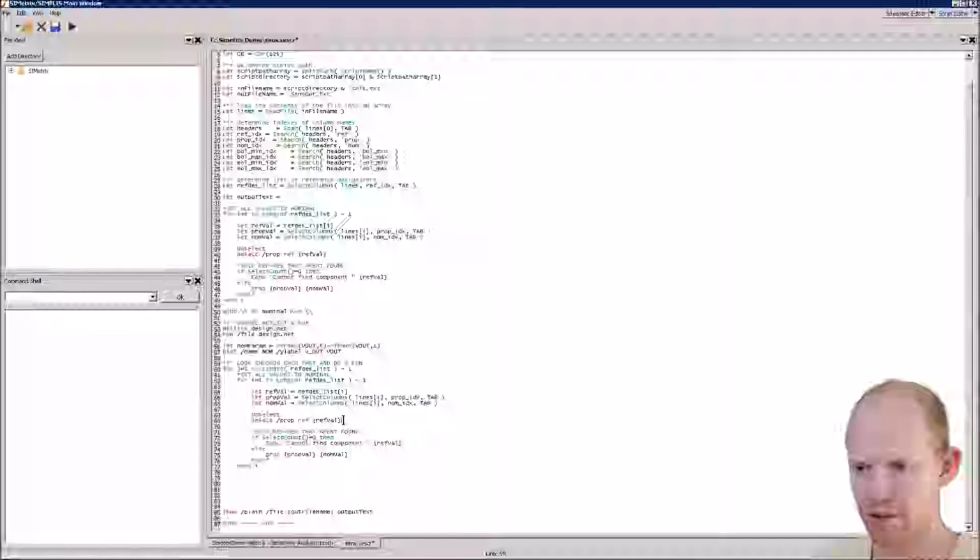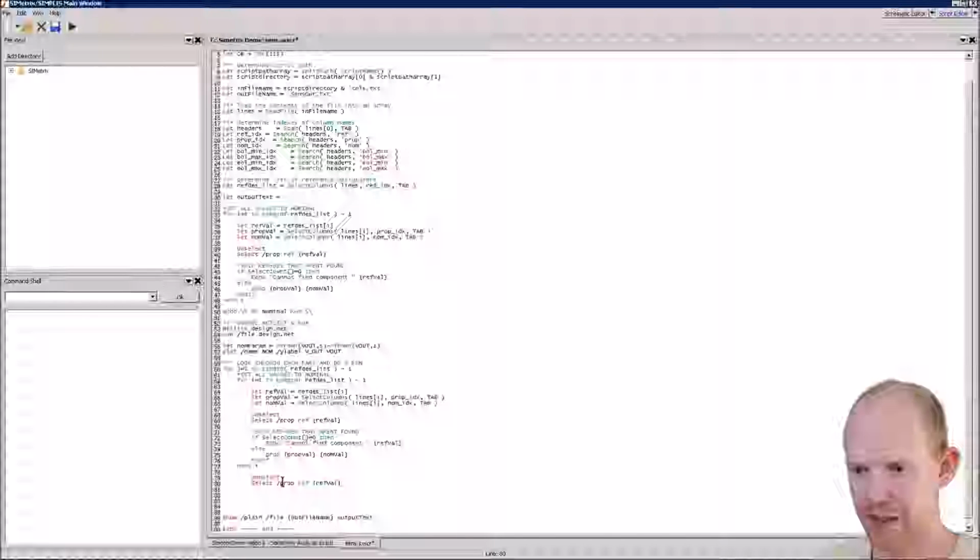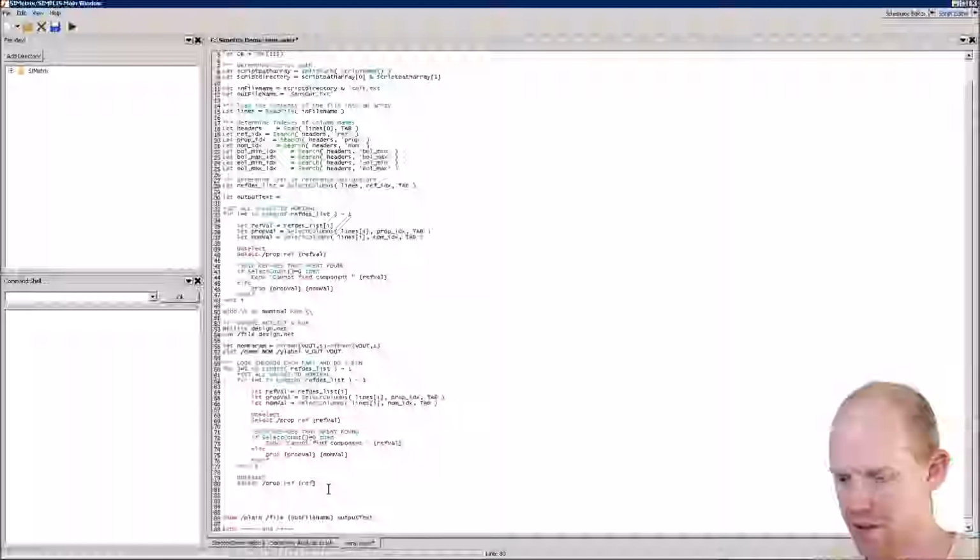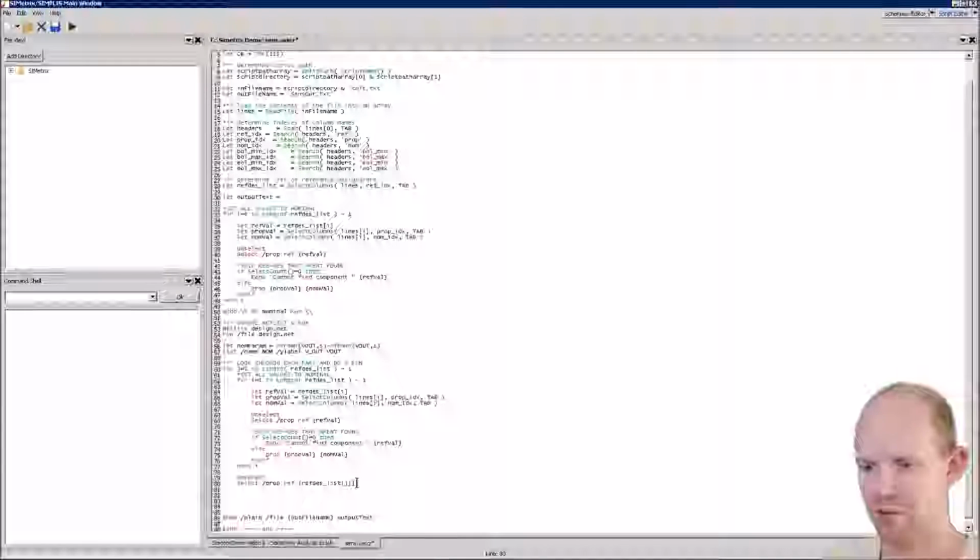And then we want to do this unselect, select again down here, shift tab to get that in line, and instead of setting the current value at this point, we want to do the current value that we are looping through in this J loop. So that's going to be refDesList, and that's going to be J, the jth entry in the refDesList.